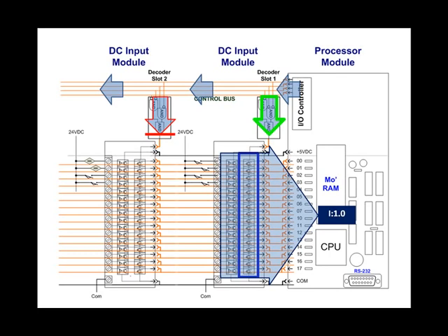These 16 states represent the 16 inputs wired to the card in slot 1 and are recorded in a 16-bit word in memory. This location in memory is permanently associated with slot 1 inputs or outputs. Now when I say permanently associated, I mean the pointer or the tag name I:1.0 is permanently associated with that circuit card.